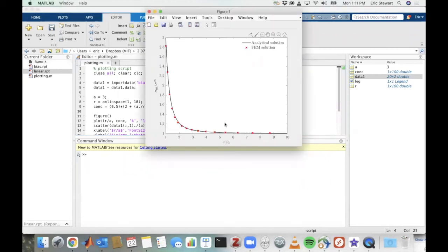And you can see that we've gotten much, much closer to that analytical stress concentration factor of 2.83. So previously we were around 2.3, and now we've got 2.83. And that's with the same number of elements along that ligament. We've just spaced them out so that they're more closely spaced where there is more spatial variation in the stress. So again, we've significantly improved our approximation, but there's still room for improvement.